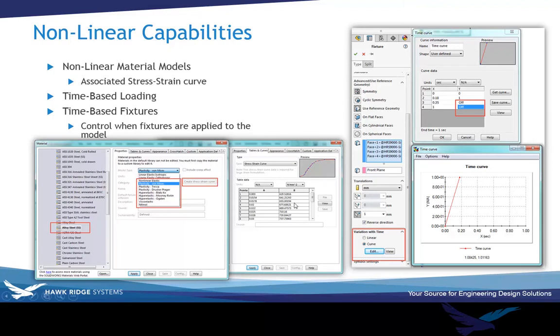That's embedded within the software. You see how the stresses are going to change due to that. Essentially what you're looking at is the plastic range of your stress-strain curve. And you definitely have the option to define your own material. Therefore, you define your own stress-strain curve if you have something a little bit more custom that the original database may not have.